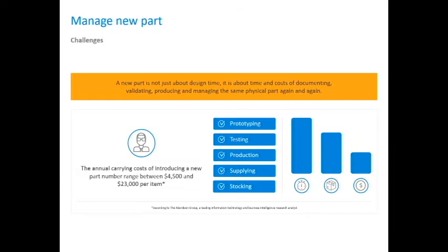There used to be third-party tools for this, to try to check for geometry in your network, and they would use different things like how many kilobytes are in the file to see if it's the same thing. But the way Inventor and Vault work now, and this is primarily an Inventor tool dealing with part files and assembly files, we're looking: is there the same exact part out there, regardless of what the name of it is?